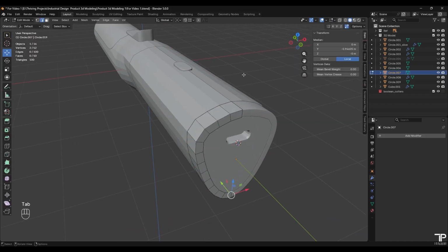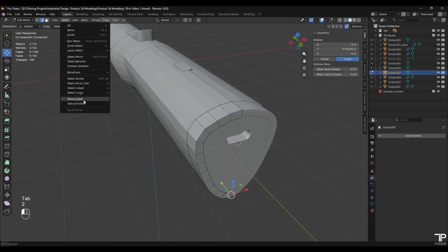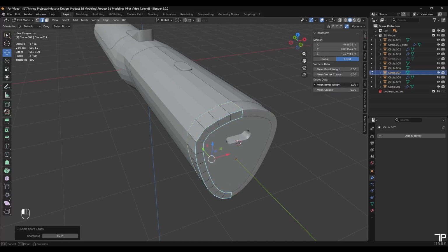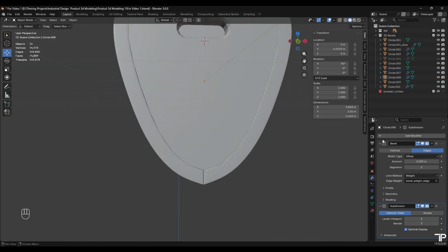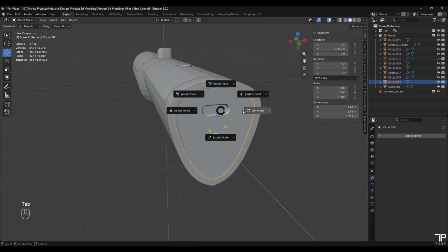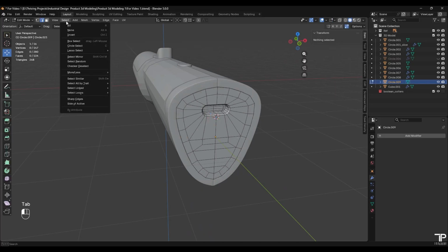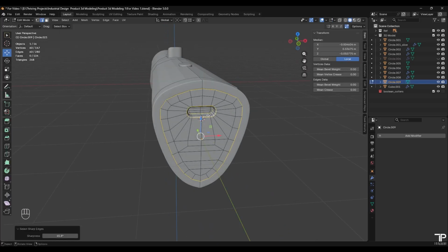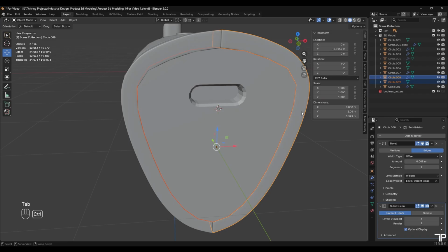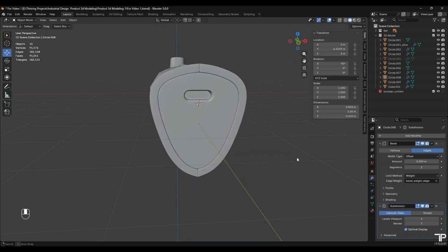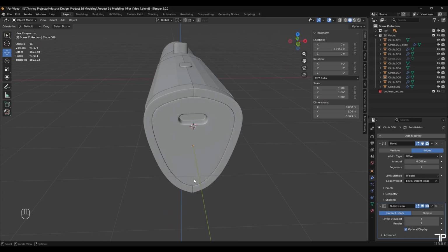And similarly here also, select sharp edges, add bevel weight to them, and I will simply select this, press Ctrl L, copy modifiers to copy the bevel modifier and the subdivision modifier. Similarly, I will select the sharp edges, then add bevel weight, press Ctrl L, copy modifiers. Here you can see we got a panel line.